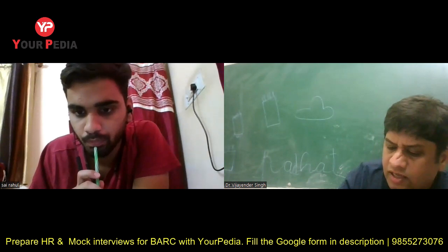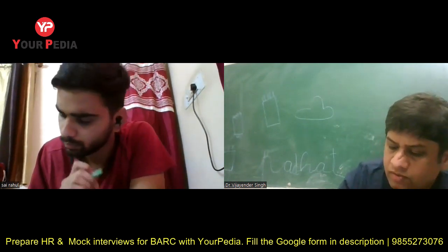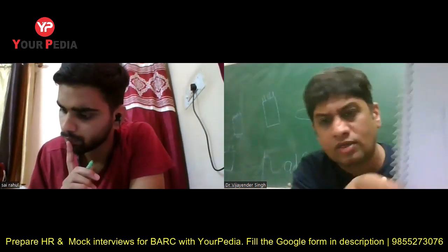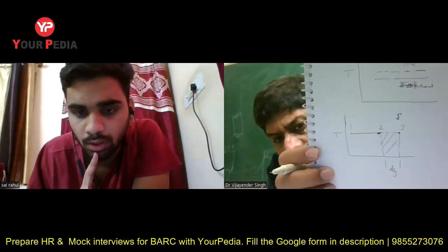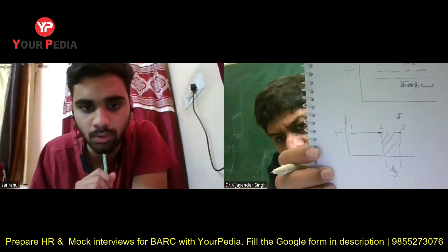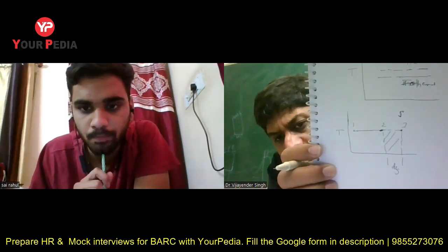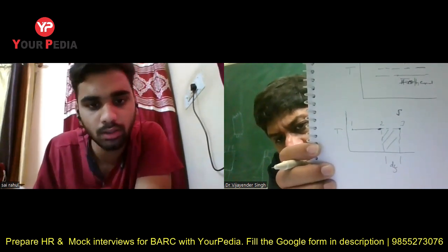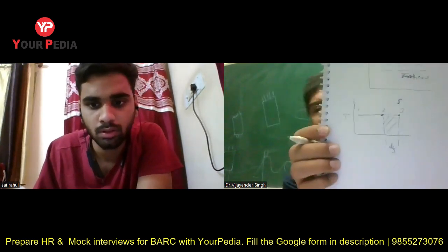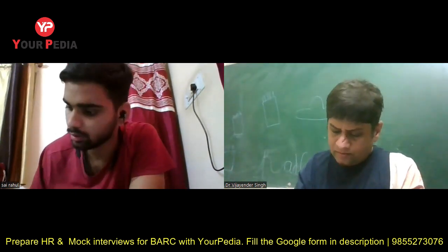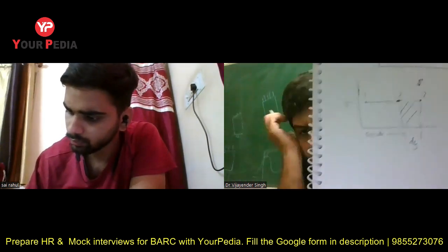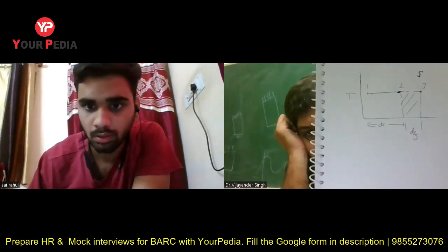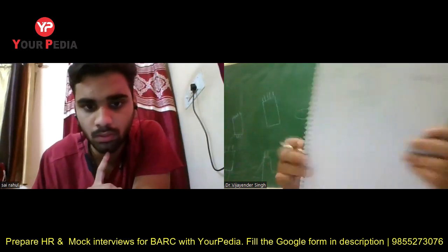So real process and reversible processes. So 1 to 2, as you can see in the diagram, is a reversible process, right? Yes, sir. 2 to 3 is a reversible process. 1 to 3 is a real process, right? Yes, sir. So 2 to 3 is the entropy generation. Can I say that? Yes, sir. So 1 to 2 is entropy change as you have calculated. Yes, sir.